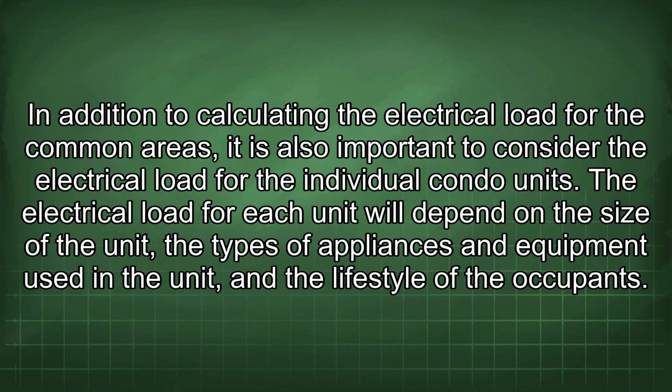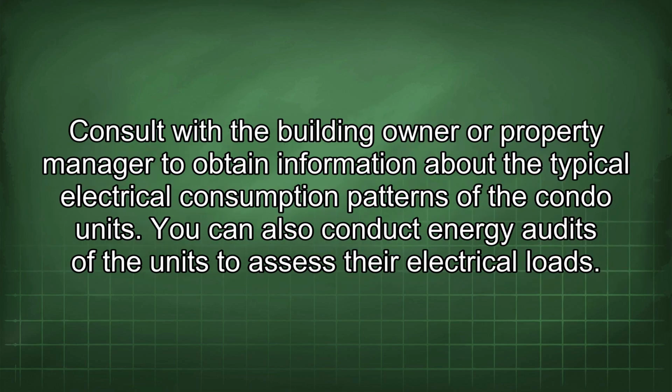The electrical load for each unit will depend on the size of the unit, the types of appliances and equipment used in the unit, and the lifestyle of the occupants. Consult with the building owner or property manager to obtain information about the typical electrical consumption patterns of the condo units. You can also conduct energy audits of the units to assess their electrical loads.